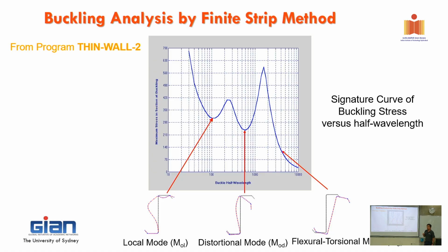So usually when we calculate for the effective width method, we take the flat, excluding the curve, using d by d. So we treat it as a plate and local buckling of the plate. But here, usually when we calculate for any section, the flat, like the LCR value which we get from the analysis, is less than the actual flat.